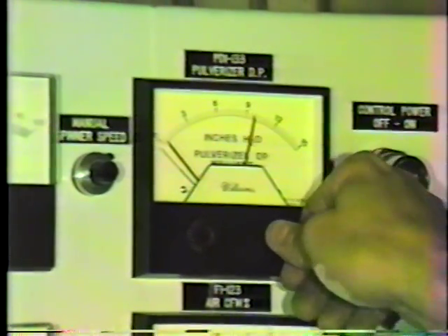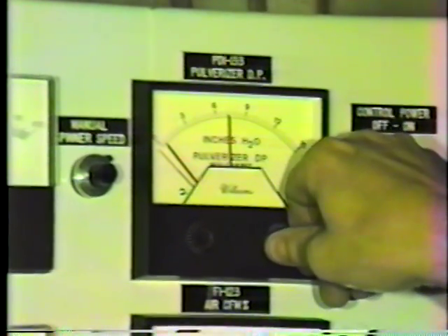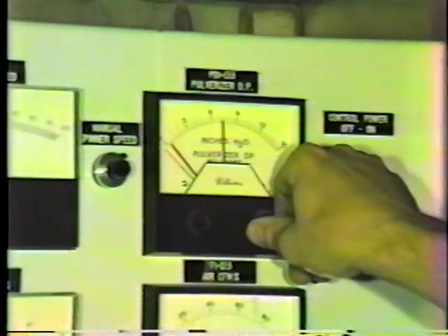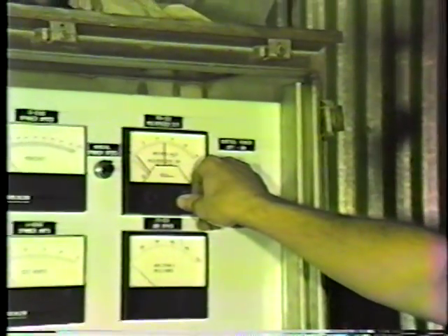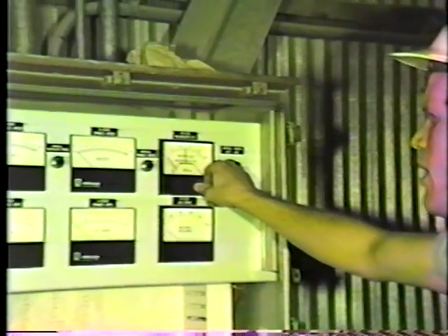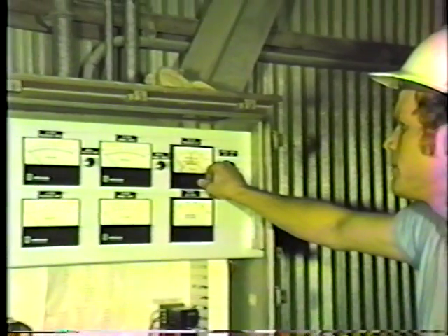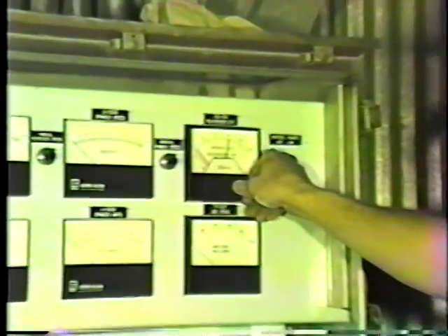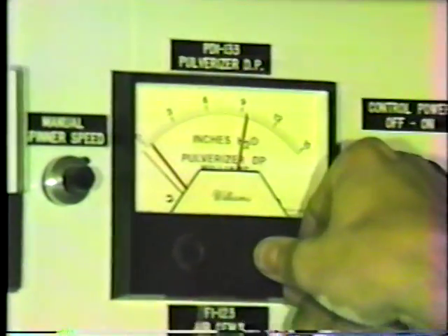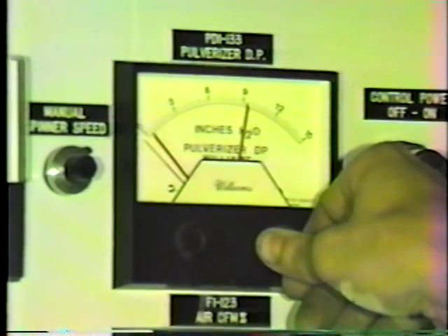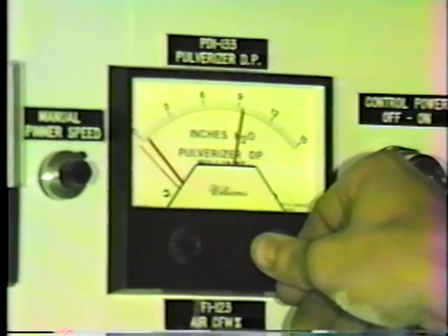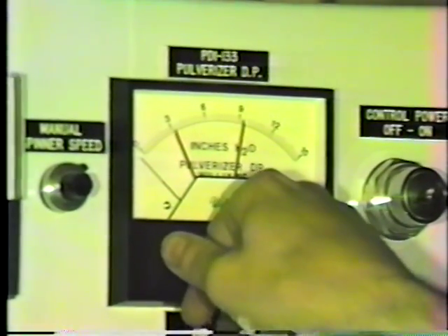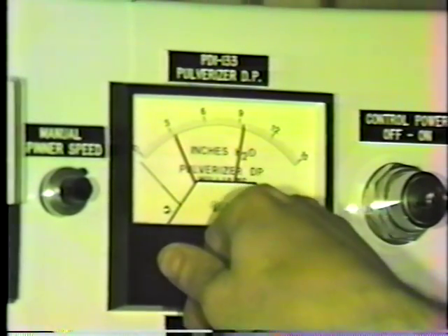And the upper set point is at the hard limit feed rate into the mill. For some reason the computer starts overfeeding, we can cut the signal through the meter. Okay, so the upper one is an override on the computer and will actually shut off the feeder should something go awry. What's the bottom one? Bottom one is our lower hard contact limit telling us that we are empty.